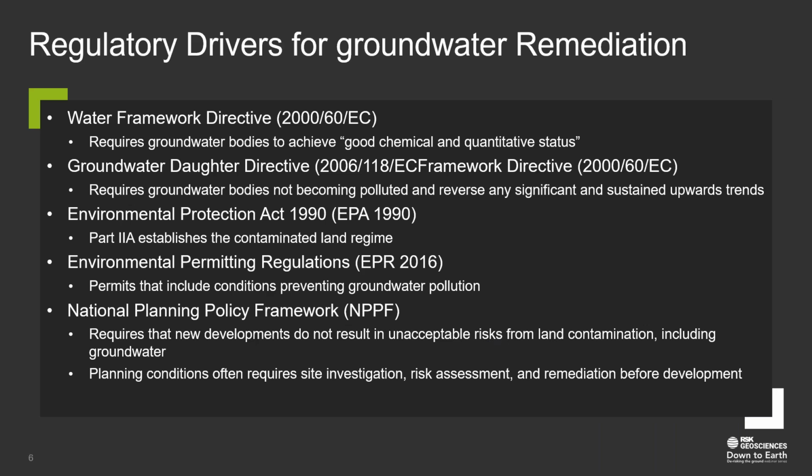The land contamination aspects are then addressed within the planning regime and Part 2A requirements. So, as a summary, you may have to manage potential groundwater contamination as part of a planning application for redevelopment, or as part of Part 2A obligations, or as a voluntary remediation, or as a regulatory requirement such as a remediation notice or anti-pollution works notice, or where a decision has been made to deal with historic contamination identified through environmental permitting site condition reports.